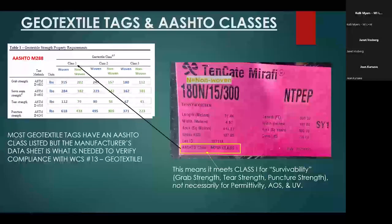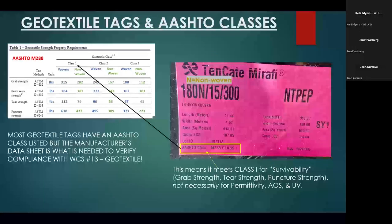So geotextile tags, I talked about the AASHTO classes, and oftentimes geotextile tags will list the AASHTO class, but we can't confuse that with our classes, because remember, for woven, they don't match up. They do for non-woven, but we have a class 4 for non-wovens that AASHTO won't mention on these tags. So, this is nice information to have, the tag and everything, but you can't approve the geotextile based solely on the tag.